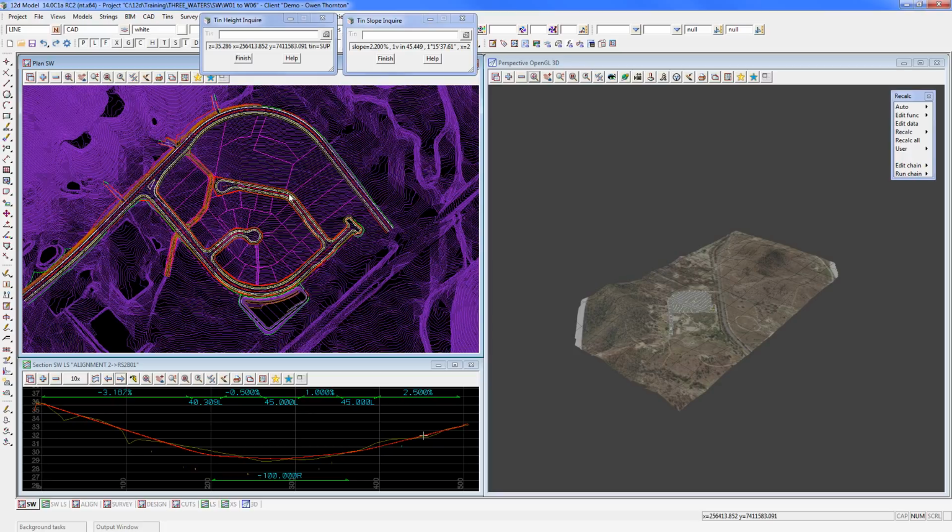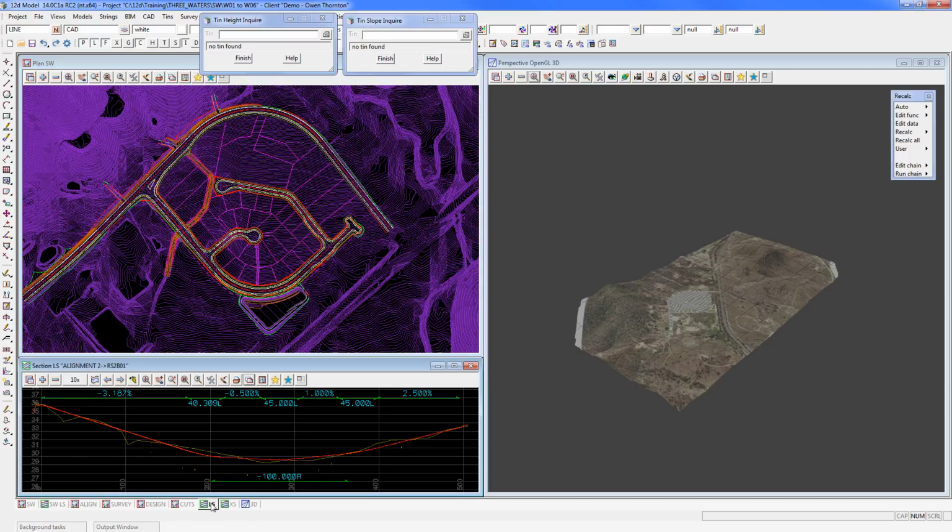Okay, you could then probably want to move down to your long section view, whether the temporary one I've got here, or the actual road long section. And I've got 1, 2, 3, 4 roads we're proposing. And the roads in a typical job like this, which is more like a subdivision design, are going to be your main conveyance mechanism for the catchments to run off into, and then we'll be providing drainage within the road network.